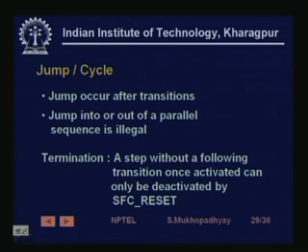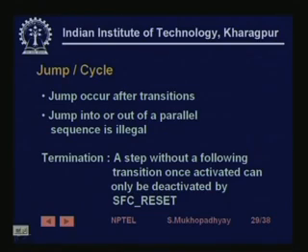Similarly, last, you may have termination of a program. So a step without a following transition. If you have a step out of which there is no transition, then it's a dead state, and once it is activated, it can only be deactivated by a special instruction called SFC reset.